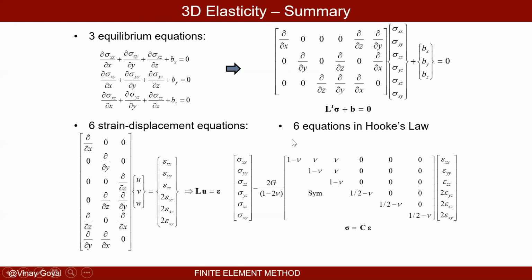So if I take L bold transpose and transpose that, I get L bold. In essence, L bold is this, and the transpose of L bold is that. The deflections are unknown, so U bold, and this is the strain vector epsilon bold. So L bold times U bold equals strain bold. Great. Now I have a relationship of strain in terms of deflections in a very compact manner.